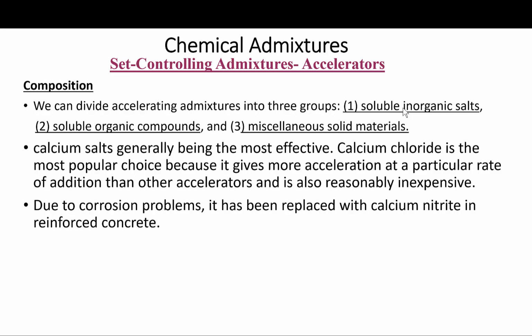So recent research shows that its reaction with Portland cement is rather complex. So it can cause a retardation or a flash setting depending on the amount used. And again, to avoid surprises from these admixtures, first of course, you have to consult the material manufacturer, the ready mix supplier, and also do trial batches and testing. This is the key. Okay. So again, many more products still exist.